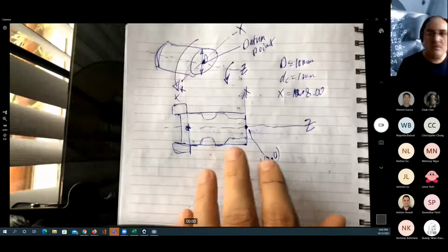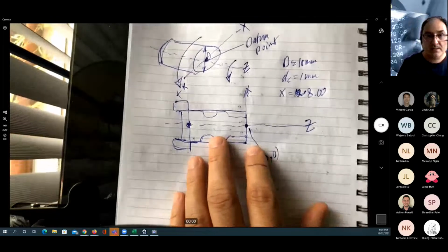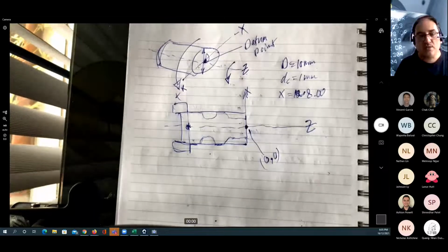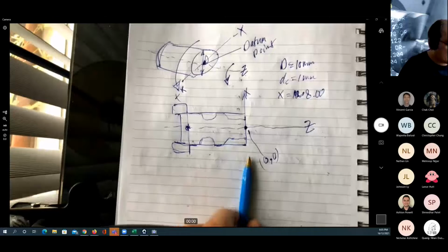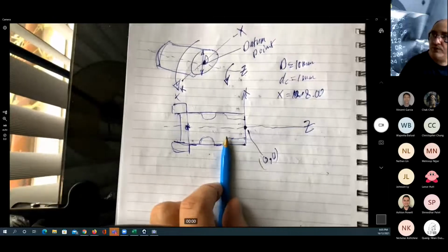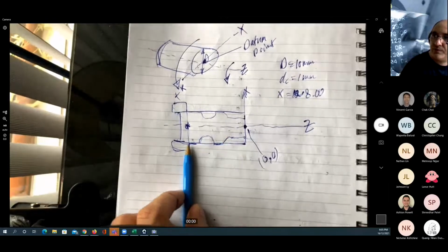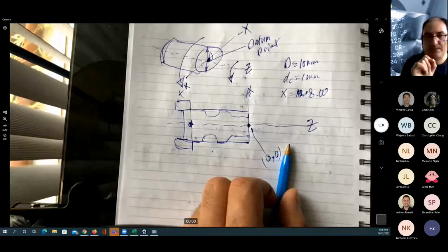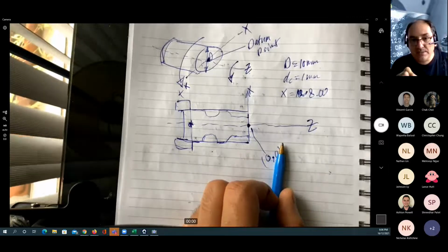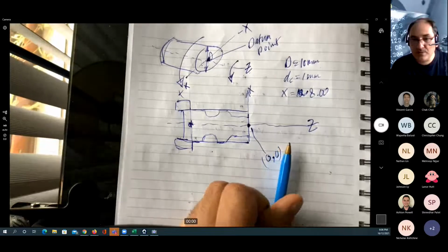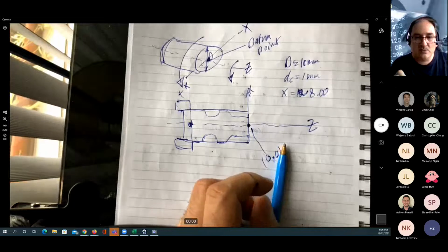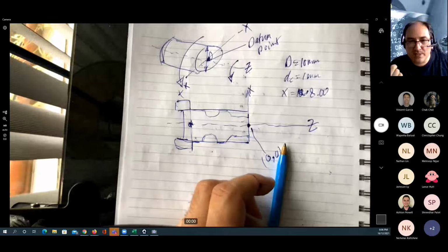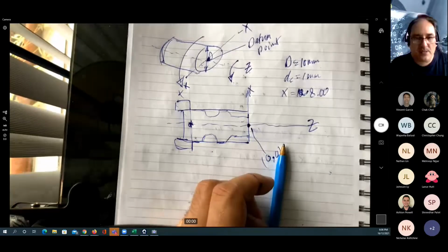Now we need to find out how we can remove that. The turning operation has nothing to do with the milling operation, where we simply set the depth of the cutting tool, move it and remove the material. Because the cutting tool, once again, has a single tip in the case of turning, we can set a very high depth of cut. The depth of cut will mainly depend on the cutting tool material we're using and the material we are cutting.